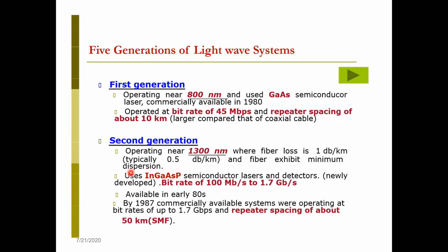The pulse has scattered, means the width of the pulse increases. Now, when this width of the pulse increases, there are chances that the adjacent pulses overlap each other. Namita ma'am might have taught you ISI, that is intersymbol interference. That problem of intersymbol interference comes over here in the case of dispersion. Now, what happens if the pulse is totally dispersed?